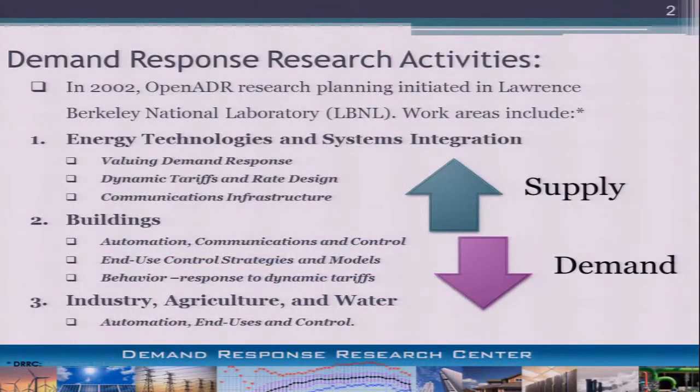So this is all about demand response, which we consider to be the ability to remotely reach out to active loads and request moderation or reduction of loads based on system-level concerns. And we've been involved in this area for quite some time, and back in 2002, for example, we started working on the development of an internet application-level protocol called OpenADR, Open Automated Demand Response, that was essentially an attempt to codify the particular data structures that are needed to communicate to loads and indicate what sort of demand reduction was being asked for and what kind of demand reduction was being responded to.